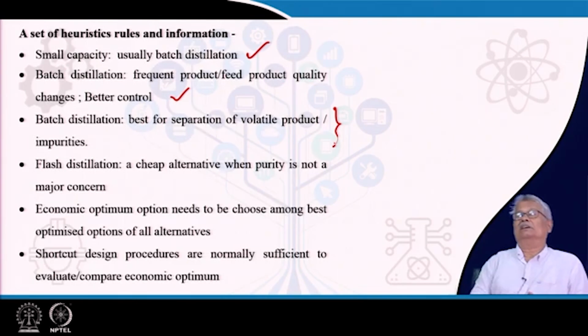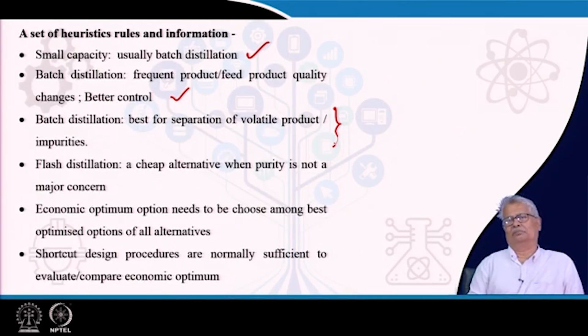But remember, while distilling something in batch, you have to ensure that your heating element remains submerged when the last drop comes out. That means you cannot have 99% of the distillate in a batch operation. Possibly you can go up to some 15-20%. That's a practical limit, mainly posed by requiring the heating elements to remain submerged in the batch still.